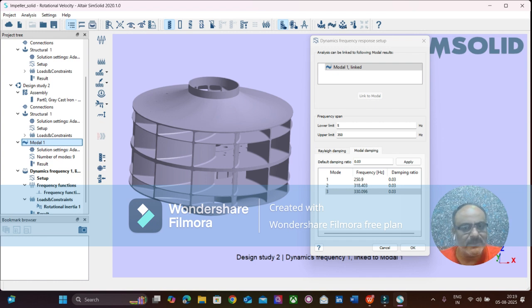and as what we saw from the previous model simulation, we said that omega is equal to square root of k by m. Omega is nothing but the angular velocity, which is equal to square root of the stiffness divided by the mass. Now we have the overall mass here, which is almost 0.7 tons, and then the stiffness, and the material is mild steel, and that has got a stiffness. So everywhere you will find that stiffness is playing a main role.